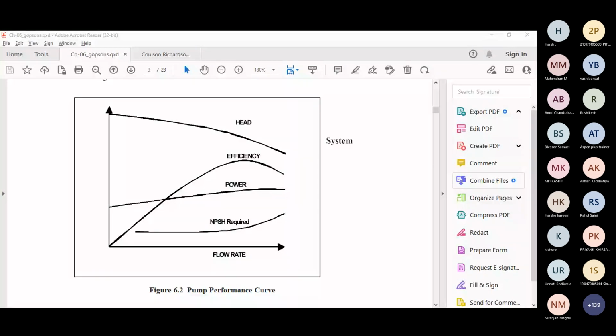Right. So suppose you are purchasing a pump and you are saying that you will be pumping this particular fluid. That meter of liquid column is with respect to that particular fluid only. So if the fluid changes, this meter of liquid column might change, right? Suppose there is a pump of 10 meter of water column. It is fixed, it is 10 meter always. If I pump mercury, then with respect to mercury, that head will be 760 mm Hg. So the value is changing with respect to the unit also. But if we convert 760 mm Hg of mercury, that is again 10 meters only in terms of water column.